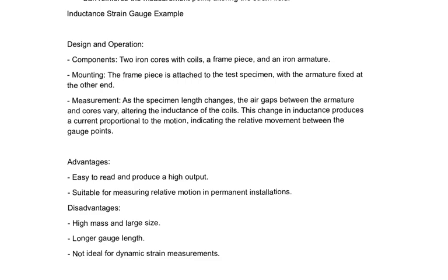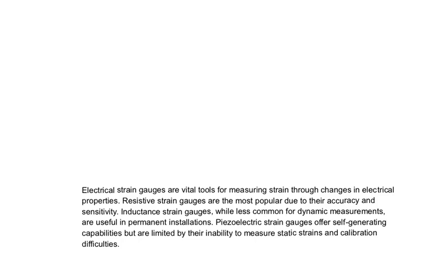By this, we can say that electrical strain gauges are a vital tool for measuring strain through changes in electrical properties, and resistive strain gauges are the most popular due to their accuracy and sensitivity. Inductance strain gauges, while less common for dynamic measurement, are useful in permanent installation.